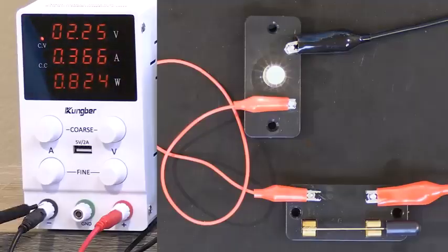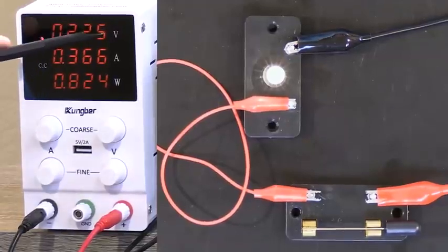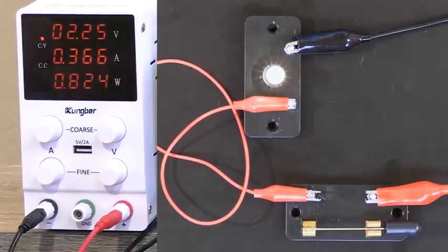In a circuit, the reference point for this voltage on this readout is between these two terminals. So it's telling me there's 2.25 volts, which, we'll talk about units in a minute. Volts is the unit of push in a circuit, right? But it's the unit of push that exists between these two wires. Voltage is always between two points. You cannot measure voltage at a single point.